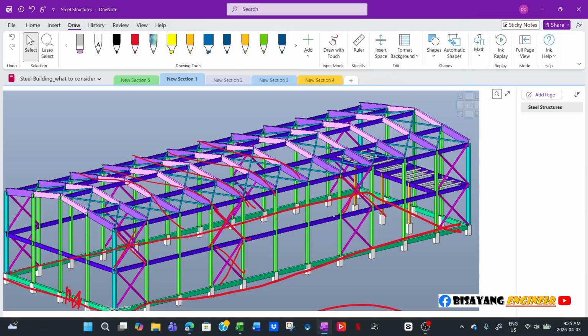Basically he said that when they design this kind of structure, they will always assume that there will be upgrades in the future. There will be changes in loadings and whatnot. So they will usually size the frame at double the required capacity at that particular time.